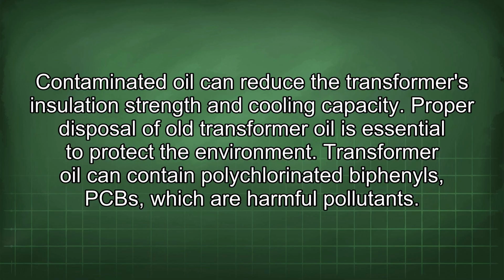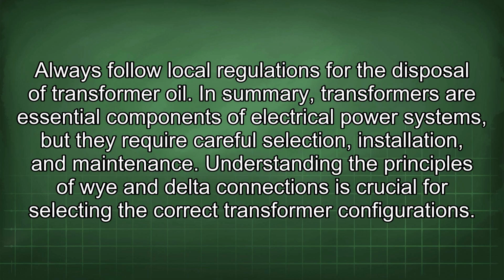Proper disposal of all transformer oil is essential to protect the environment. Transformer oil can contain polychlorinated biphenyls, PCBs, which are harmful pollutants. Always follow local regulations for the disposal of transformer oil.